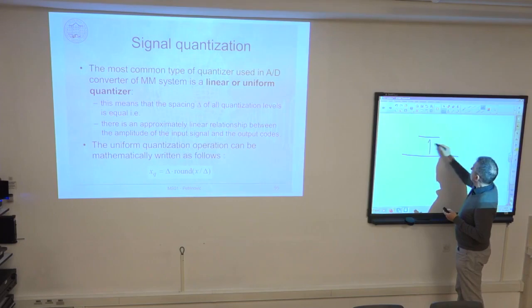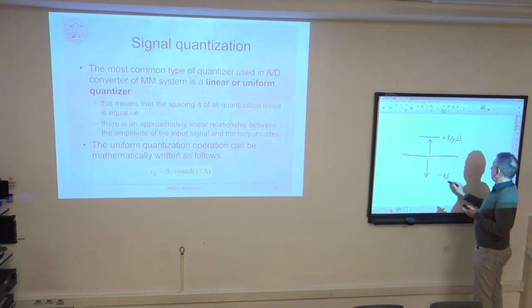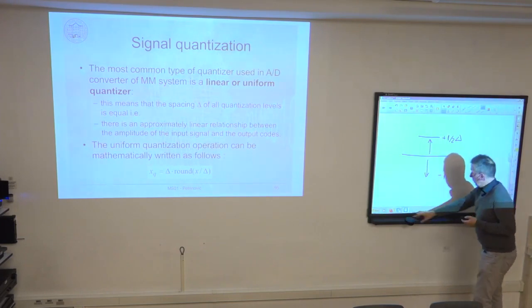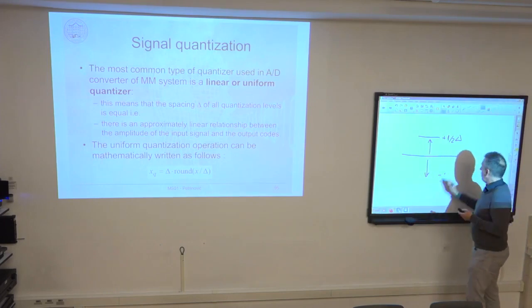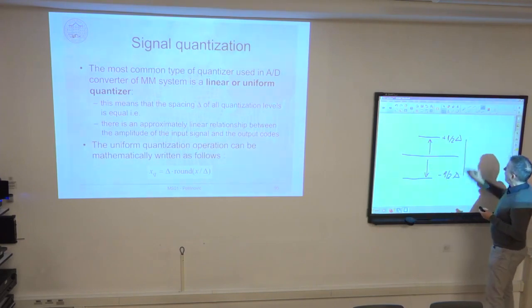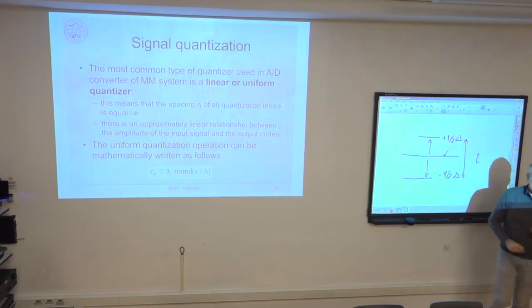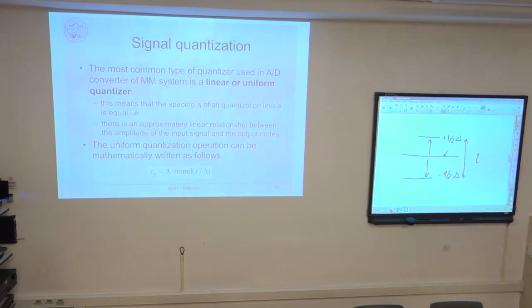This is plus 1/2 of the delta. This is minus 1/2 of the delta. So the whole range is quantized to the same value I, corresponding to the central value. And the error is at most plus 1/2 step size, or at least minus 1/2 step size, due to this rounding to the nearest integer.